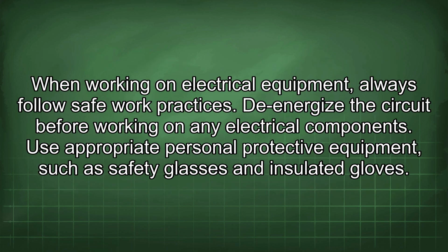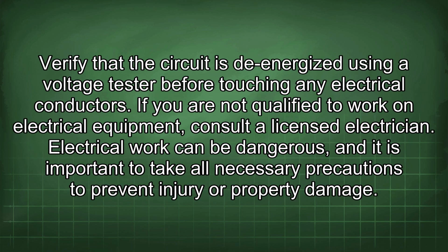When working on electrical equipment, always follow safe work practices. De-energize the circuit before working on any electrical components. Use appropriate personal protective equipment, such as safety glasses and insulated gloves. Verify that the circuit is de-energized using a voltage tester before touching any electrical conductors. If you are not qualified to work on electrical equipment, consult a licensed electrician. Electrical work can be dangerous, and it is important to take all necessary precautions to prevent injury or property damage.